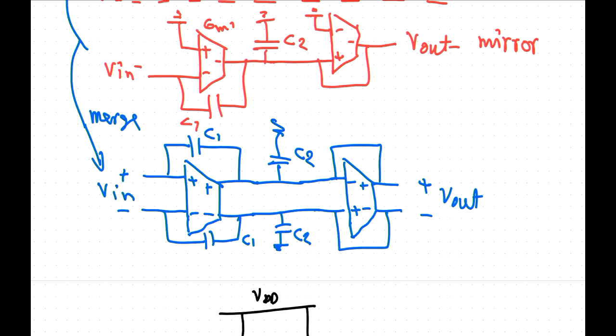Positive feedback? Well, it does actually. That is true. It's okay to have positive feedback if you don't have too much. But you can work out the transfer function. I don't know if I worked it out. Yeah. Because the capacitor actually contributes to the phase shift. It does. It introduces a zero in the transfer function. So they're not strictly like a 180 degree phase shift.